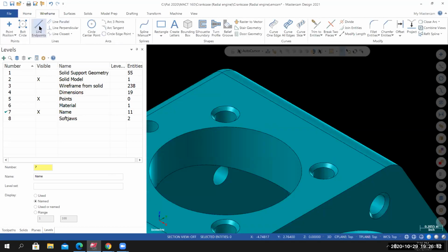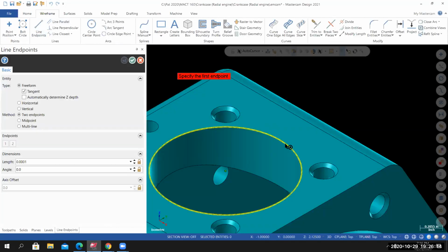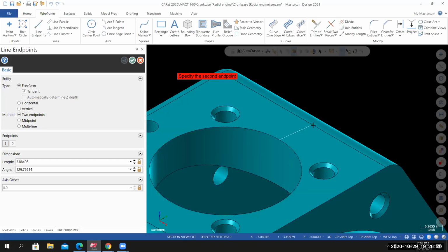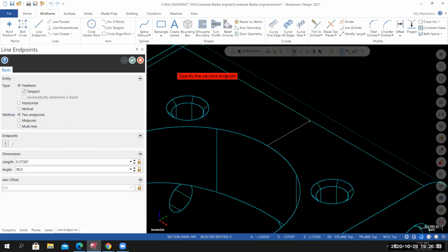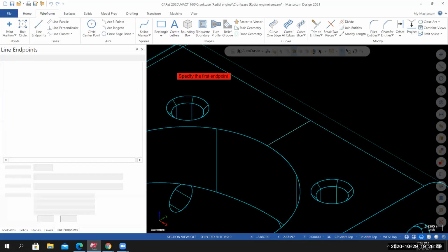Yeah. Nice. So I want to go from the quadrant right there and then perpendicular. Is it letting you lock onto that? No, see the solid one, not that one, this one right here. Yeah, I clicked that one and I was able to lock on. You have to watch out because you don't want to lock onto the midpoint, because it's an angled line at that point. I want it to be perpendicular. Okay, so I could just eyeball it. Not that big of a deal.